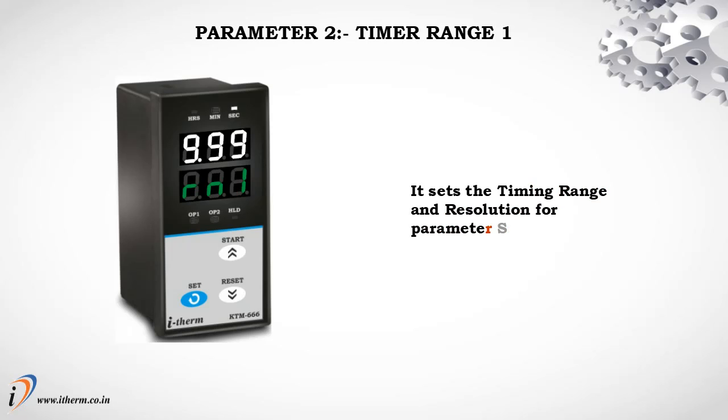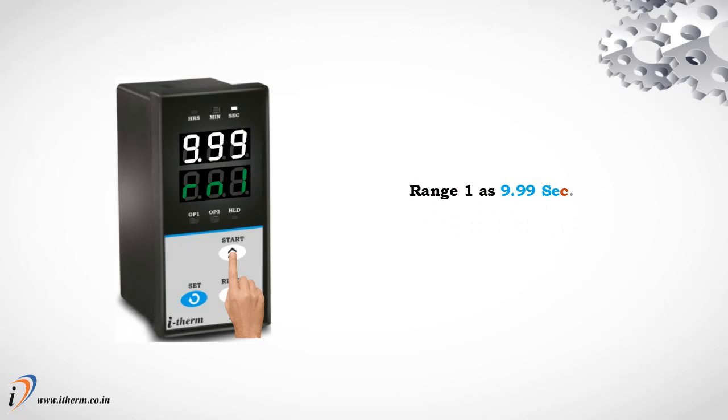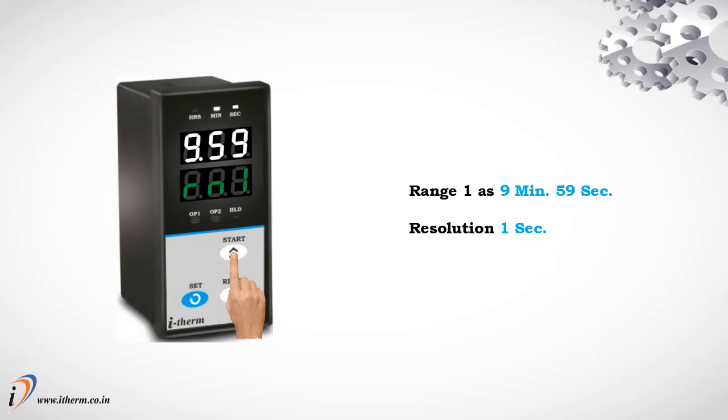Parameter 2, Timer range 1. It sets the timing range and resolution for parameter set time 1. Range 1 as 9.99 seconds. Resolution 0.01 seconds. Range 1 as 99.9 seconds. Resolution 0.1 seconds. Range 1 as 999 seconds. Resolution 1 second.